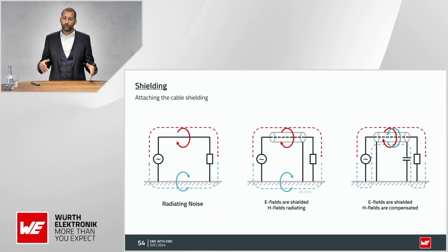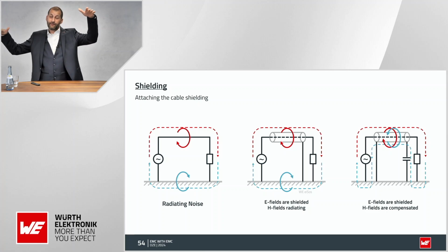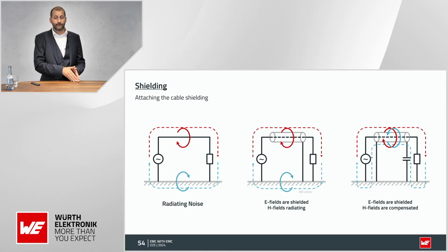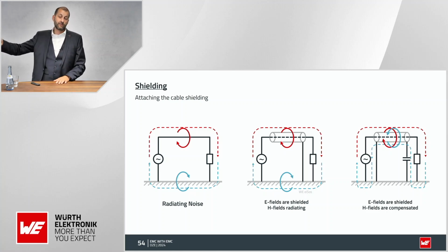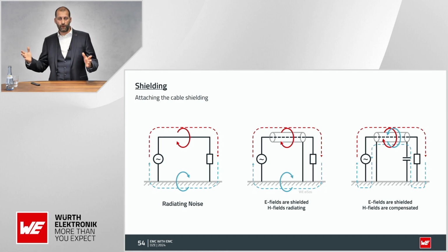So of course, we always speak about ground as this 0 volt potential, but is it really 0 volt? Well, in an ideal world, yes, but electronic engineering is never ideal. So you probably have a difference. A difference in voltage will create a current. So in this case, maybe you should switch to something else. Maybe one-sided shielding is better. Or you go completely to glass fiber connections, or something else.